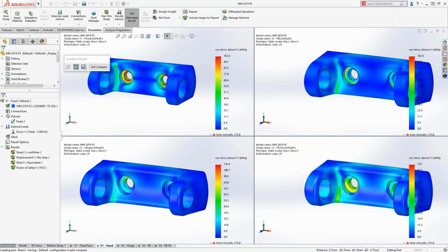So we're not introducing that artificial stiffness. The worst case would be where you see the rigid, where it's absolutely locked them all together with the fixed requirement in the top left-hand corner, and that's introduced a ton of artificial stiffness. So this gives you kind of an idea of why distributed loading is important. It gets you better results that are more realistically representative of what's going on in the real world.